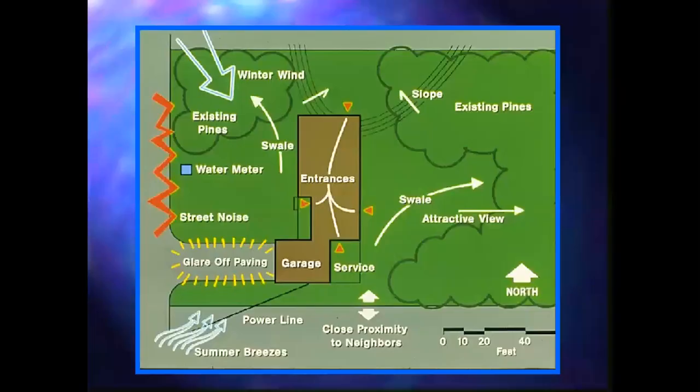Take a look at the site analysis. Know your site, where the shade is. Some areas, like around paved areas, there's glare off pavement. Look at the topography, the views, proximity to neighbors, and so forth. And you may have your front area and your private area out back, and an area where you keep your garbage can, your service area.